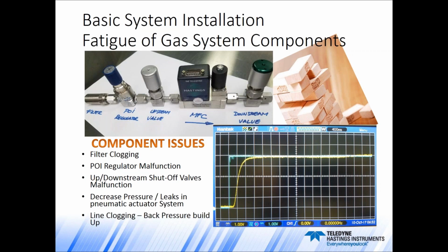And on the right graphic, we have recorded, with light blue, the set point delivered to the flow controller that goes straight forward from 0 to 100%. And then the yellow line represents the output of the flow controller that slowly and nicely follows in a curve format, gets into the 100% without any kind of overshoot, and then stays there in a stable manner, delivering the necessary amount of gas, the prescribed amount of gas, into the process.